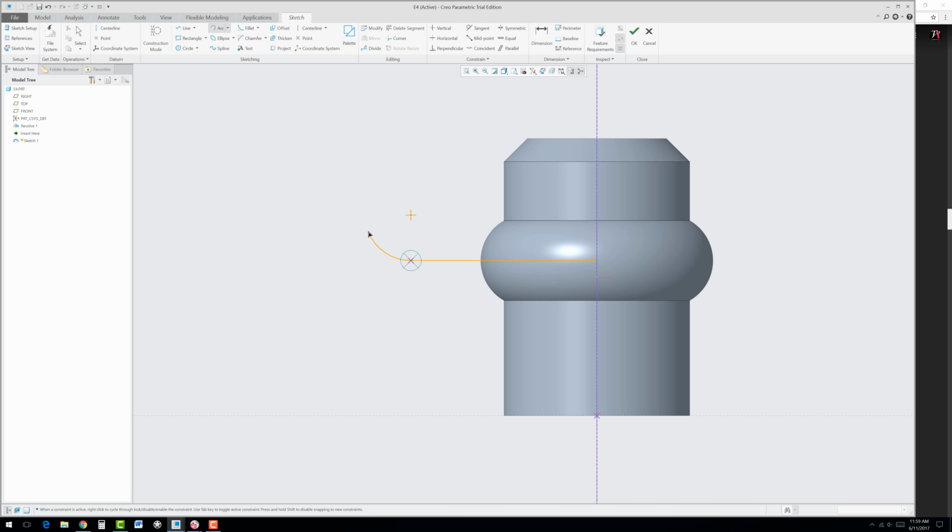Now if you want, you can snap at a 90-degree angle here. However, just be aware later we'll have to delete that. Otherwise, if you are less than 90 degrees, you might be a little bit better off. But let's see what happens if we snap at 90 degrees. Click there. Now click on this and drag this up and to the left, and you will be able to snap again that arc 90 degrees to the center. Click, and now go to the line tool and draw a short little line off of there, and middle click.